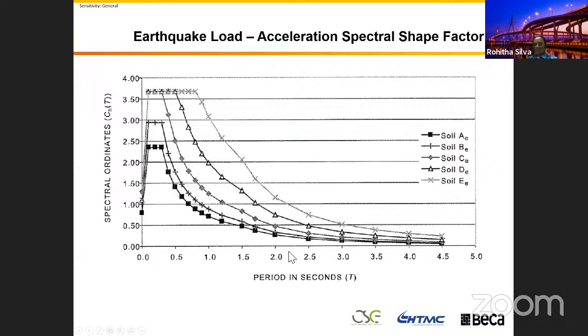But if your natural period is getting closer to this peak value, it's better to change that. You check your design close to the maximum value as well, not the average value. When you get your design spectrum and compare your design, in my experience the earthquake is not going to govern the design. You will see that when we go to the load combination part.